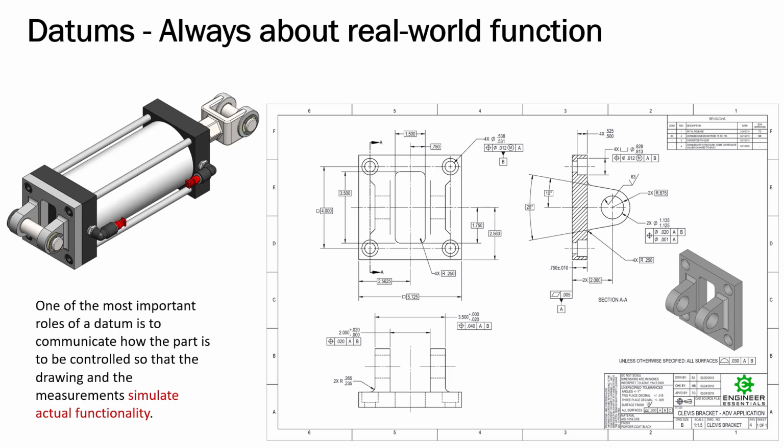Now, like I said, this most likely will not be optimal for machining. We understand that, and machinists understand that as well, as long as they understand the GD&T that's on the drawing. But in the order of the machining process, and we talk about this a lot in training, even though this is the primary, machining is not going to come in here and machine this first. That's not going to happen, so that they can get this all accurate. They're not going to do A first.